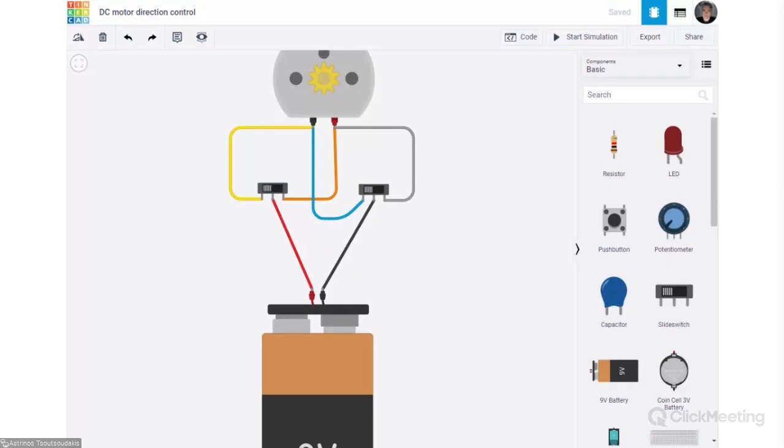this is also how we test LEDs by using a multimeter. We connect the positive and negative terminals with our multimeter, and there is just a very dim light, but it is just enough. It will not work for white LEDs for sure, or blue, but for red, it is a way to test your students' lemon or potato battery.